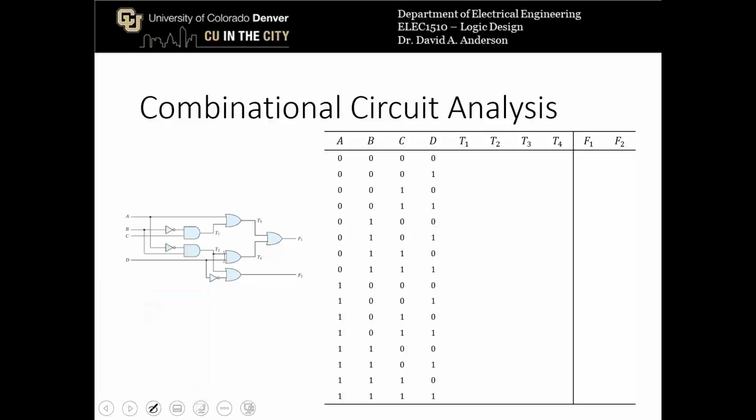So let's first write out the logical expressions for T1 and T2. The T1 subcircuit output is going to be equal to B prime times C, because B first enters an inverter and then the AND gate, C just enters the AND gate, and T1 is defined as the output of that AND gate. The output T2 is defined by the logical expression A prime B.